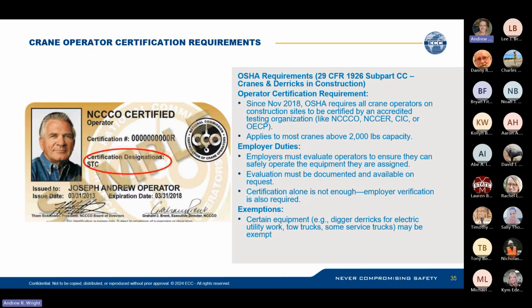So here's an example of a crane operator certificate. So you can see this handsome young gentleman, Joseph Andrew Operator, on this crane card. So OSHA requirements, operator certification since November 2018 requires all crane operators on construction sites to be certified by an accredited testing organization like the NCCCO or NCCER, CIC, or OECP. Don't ask me what all those acronyms mean. I don't know.